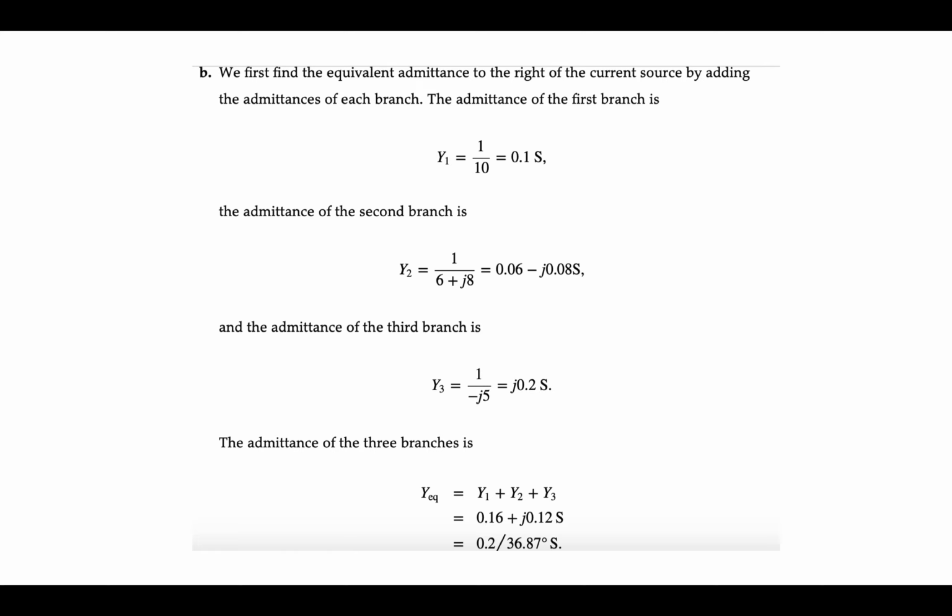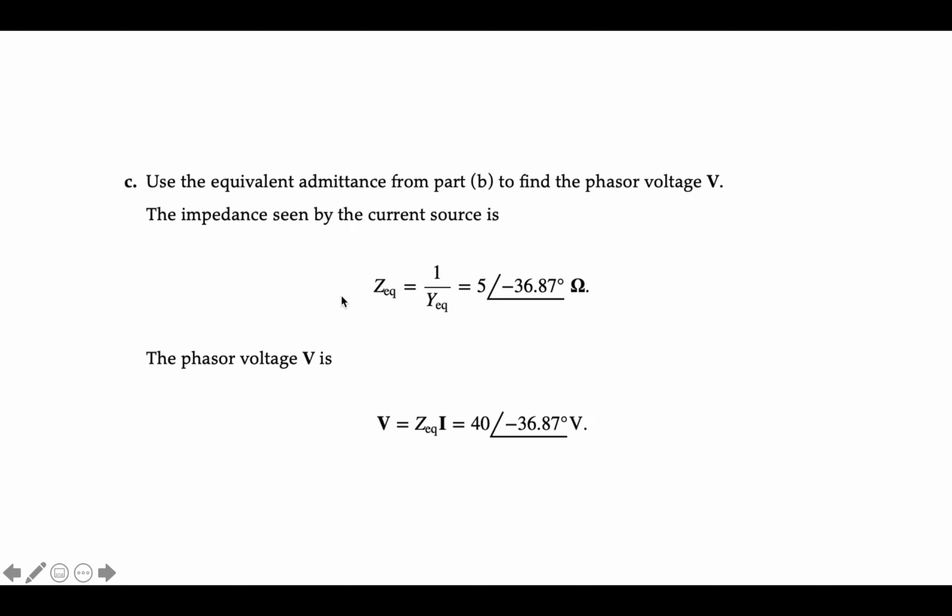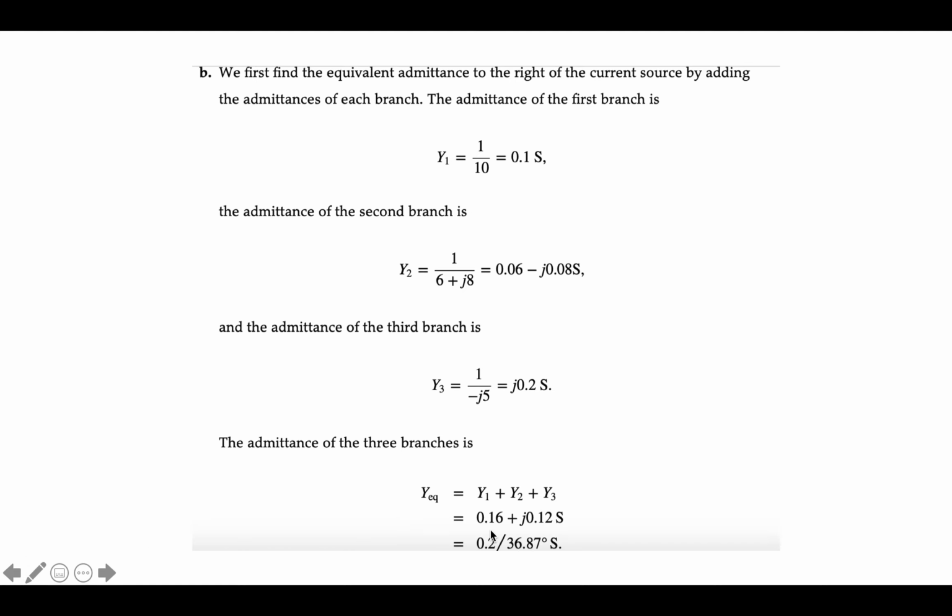Then it was converted to the phasor domain, and when I did the screenshot, the lower bar of the little angle sign, so this is not 0.2 divided by, should be an angle indicator. It just got cut off in the screenshot. So if we convert that to the phasor domain, to polar form, we get 0.2 angle 36.87 degrees. That's maybe a few too many significant digits, but it's okay.